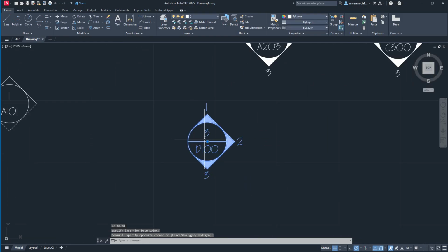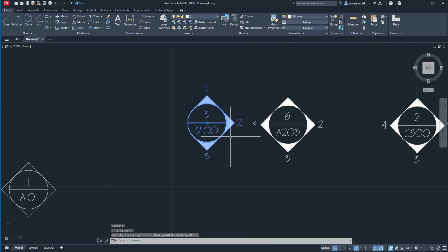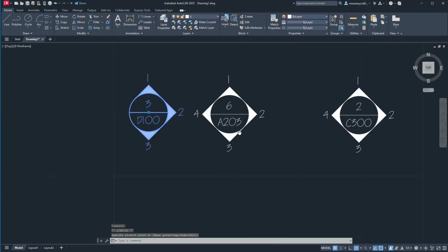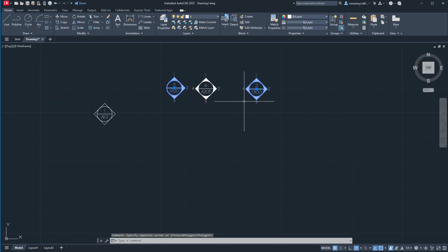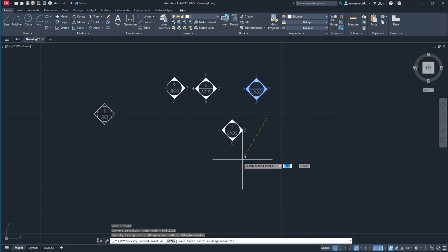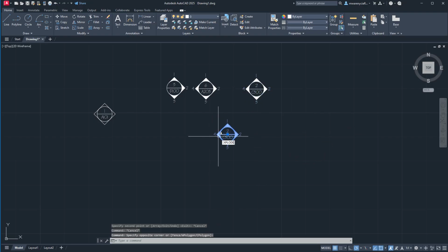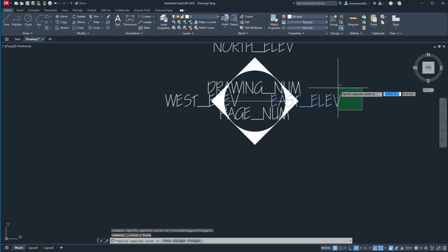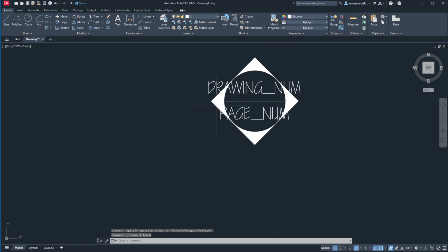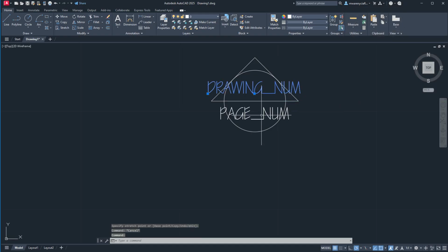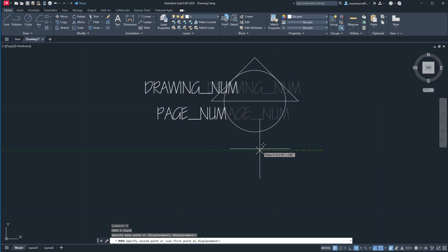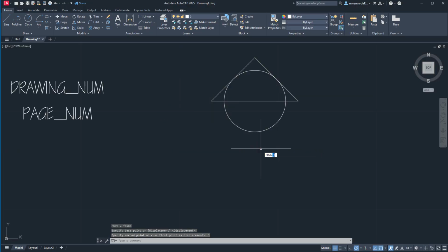So we've got these different values that we can use, or different things that we can do to that block now that we've created one that lets us use it consistently and repeatably. Similarly, now that we've got this same format here, we can come down here and just completely explode this one. And if we want to make a section cut marker, we can just modify this slightly because we've already done all the work getting the rest of this set up. Let's go and move this out of the way. Hatch.